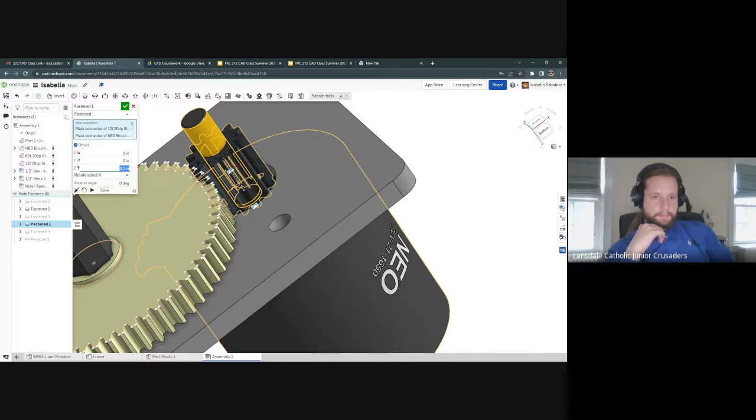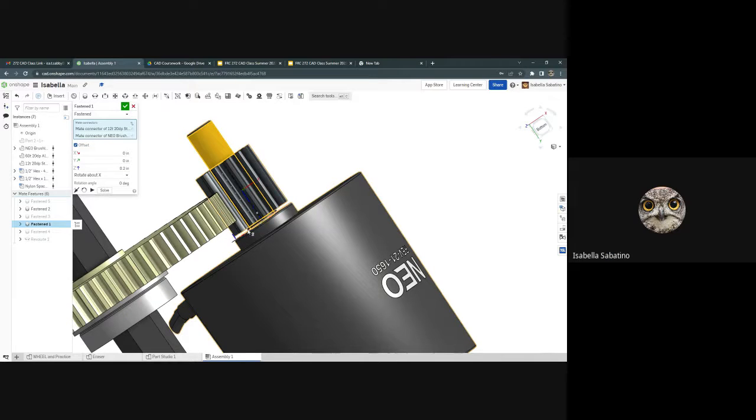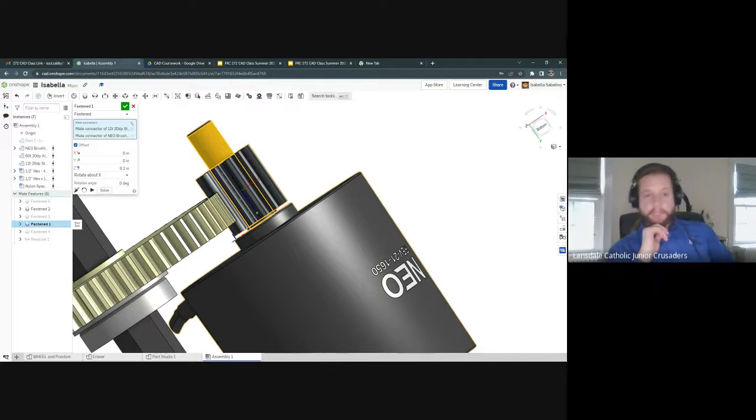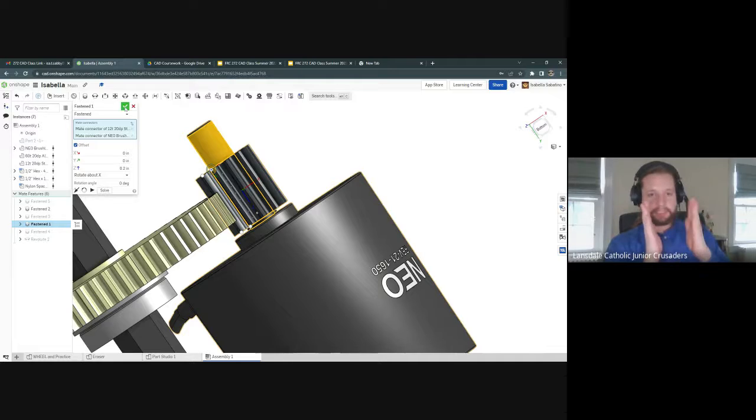We're going to try to use actual fractional values here. So I would try 0.25, but that looks pretty good. That's off of the motor. Do I want it on the motor? No, because that would have your gear rubbing against the fixed motor, right? You want the gear to only be touching the shaft and the other gears. So I would do 0.2 is fine, but I would do like 0.125, which is 1/8 of an inch. You can also type in 1/8 or 3/16 or 1/16.